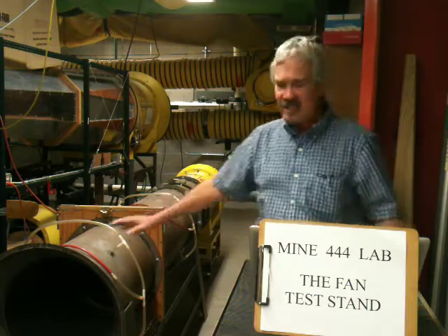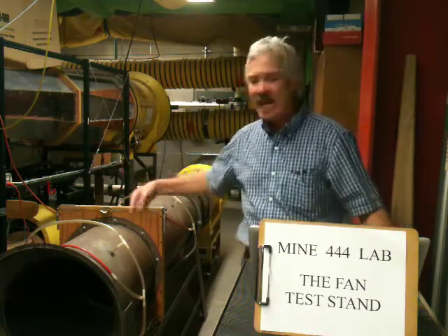At the inlet, we see an inlet bell, which serves to reduce the shock loss for the flow entering the wind tunnel, as we studied in our last lab session on the airflow demonstration unit. You can't really see it that well in the video, but we'll go over it in more detail shortly. There are 4 static pressure taps around the perimeter in the inlet section, and from the static pressure measurements that we record there, we will be able to calculate the flow rate Q based on equations that are in that British Standard 848.